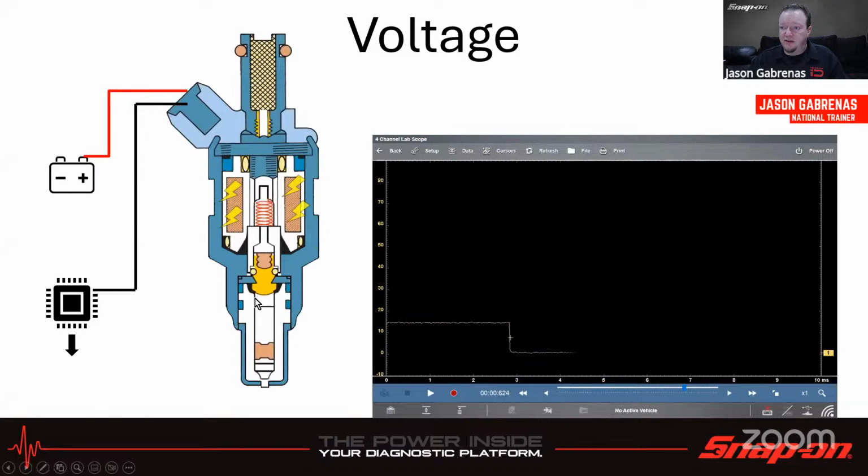So when the ECM decides to ground it, it activates the coils in there, opens it up, starts spraying fuel, and we're going to see it go down. Once it is open for however long the computer tells it needs to be, it'll snap shut, and then all that voltage that was stored in these coils gets kicked back into the circuit. So we get over 80 volts on that one.